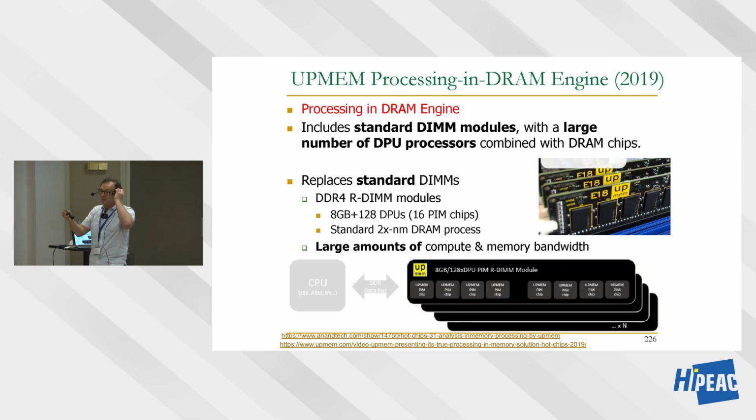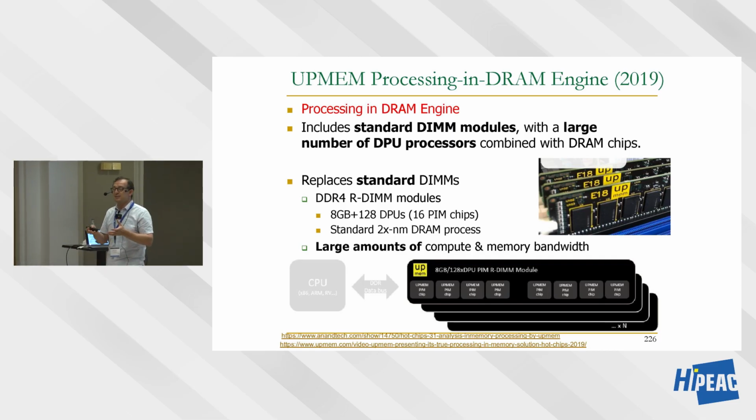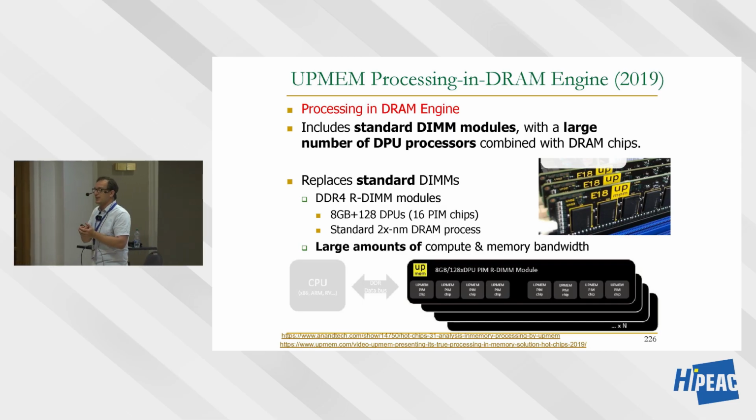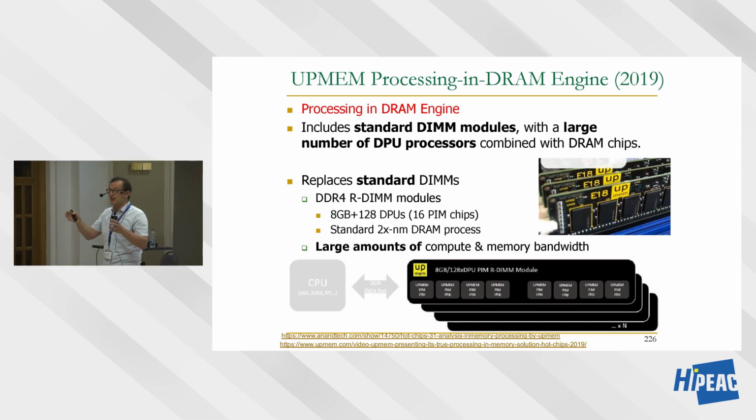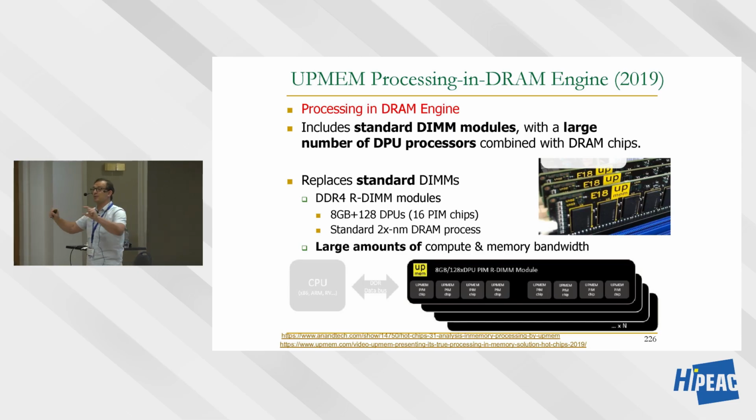Theoretically, you may not get performance because the processor has some limitations. So what are the limitations? Well, first, what are the benefits? The benefit is you can minimize the data movement, right, because you're right next to each DRAM bank. You can also reduce the energy of your program, and you can parallelize across different DRAM banks. You have lots of processors operating across different DRAM banks. So if your program can be parallelized nicely across DRAM banks, if you map your data well, this is actually great.